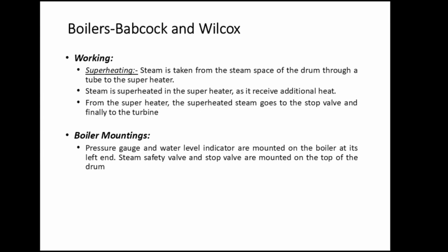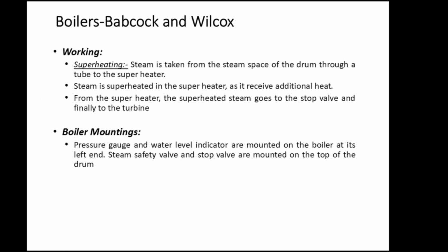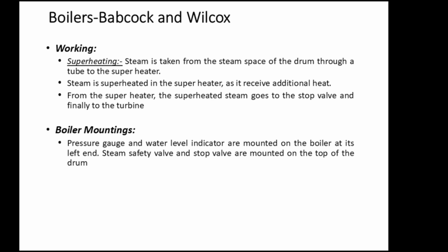Boilers. Babcock and Wilcox. Working. Superheating. Steam is taken from the steam space of the drum through a tube to the superheater. Steam is superheated in the superheater as it receives additional heat. From the superheater, the superheated steam goes to the stop valve and finally to the turbine.